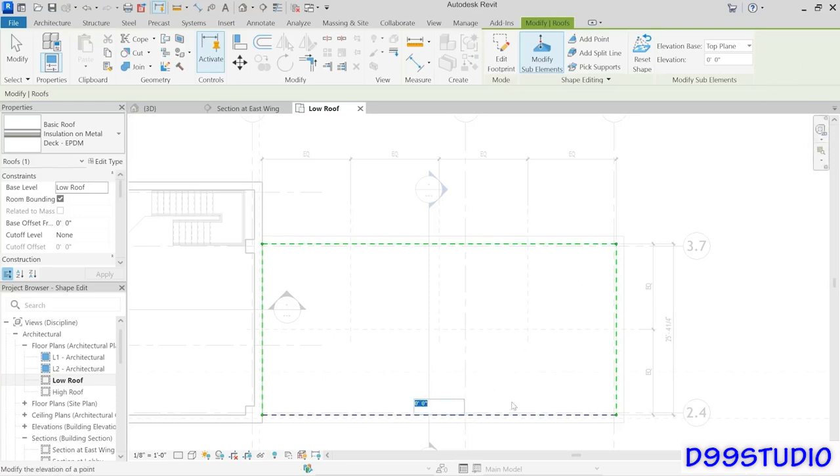So I'm going to click on this value and put in the value I want. Now, in my Imperial file, again, I'm 25 foot plus. I'm going to round it up to 26 feet so that the calculation's a little bit easier. And if I divide my 26 feet by a 1/4 inch rise, I get about 6.5 inches of rise that I need here. So that's what I'm going to put in, 6.5 inches. If you're working in the metric file, I did the same calculation and it came up with about 160 millimeters. I just rounded it up to the nearest 10. Okay, so try about 160 and you should get to the same place.